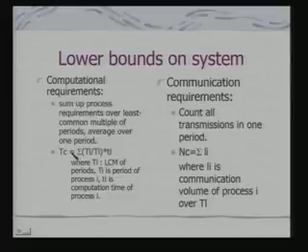So, if you look at the communication requirements, this is a kind of bound you will get. Say TL is the LCM of the periods of the tasks, because many of these tasks are periodic tasks; LCM gives me the least common multiple of these periods. If Ti is the period of each task, then dividing TL by Ti, I get the number of times a task gets scheduled. I know the processing time of each individual task.